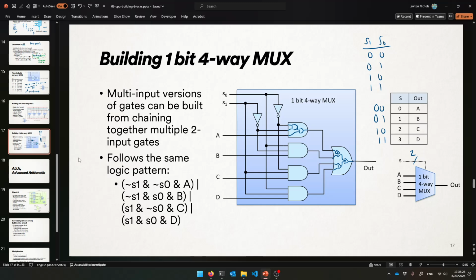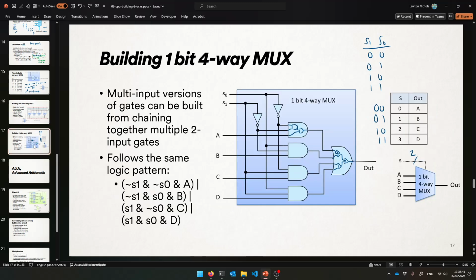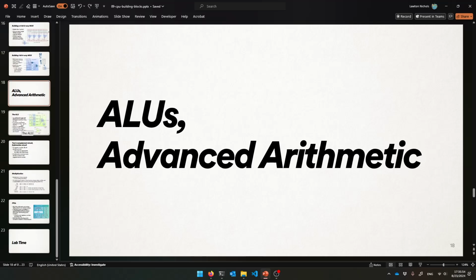All right. But I hope you can kind of understand how to build them all now. How these multiplexers can select out what we like. You can make these fatter, like you can have more options, and then also wider in the other axis, where you can take and chain a bunch of these smaller ones to take a bunch of bits at once. Okay, so yeah, I think that's what I wanted to tell you. And now we're ready to talk about a big piece of circuitry that uses adders, like we learned, and multiplexers, like we learned, to do just random arithmetic stuff.